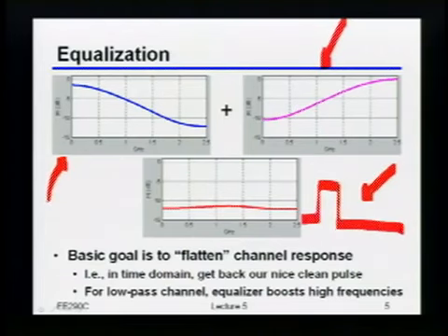So in all this, you have assumed that the channel is linear. Okay. So how do you justify it? Well, the good news is, if you remember I said way back when that usually the backplane is passive. So unless I'm doing something really, really nasty, most of the time it is indeed justified to treat it as just being a linear channel. Because unless I have voltages so large that I'm melting metals or melting dielectrics or something like that, it basically does look very much like a passive linear channel.